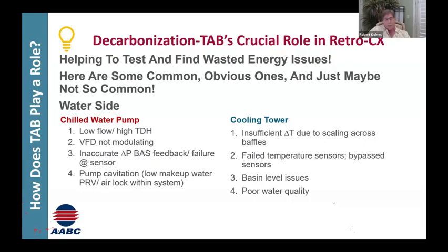The VFD may not be getting the proper signals to sequence and ramp it up, or it's in hand and somebody put it at a low speed. It operates off a differential pressure out there in the system. I've seen many times where the high-low ports are impacted, probably through chemical treatment or the lack thereof, or the petcocks are closed up and isolated if there was a leak or something. I think you've got pump cavitation there.